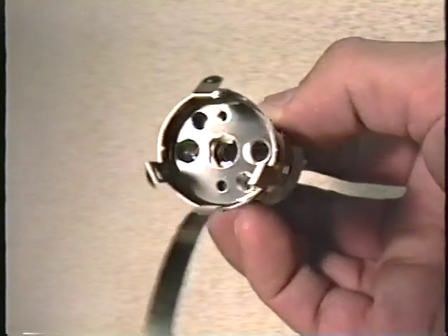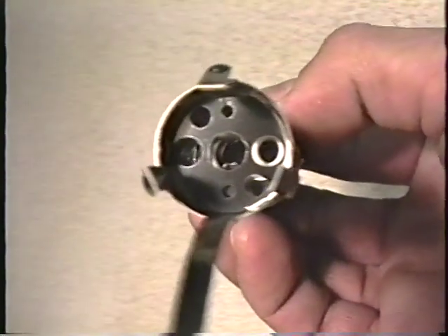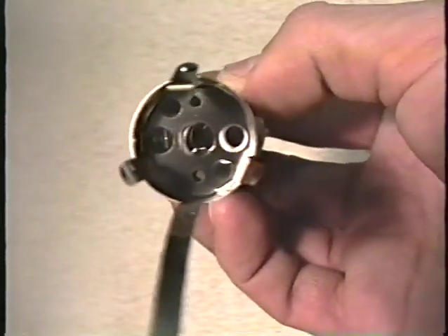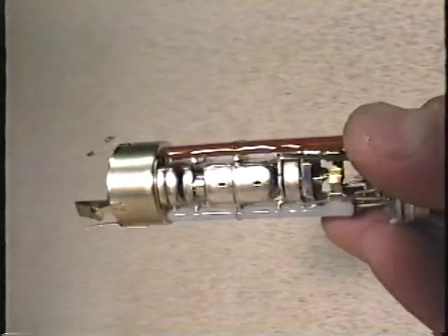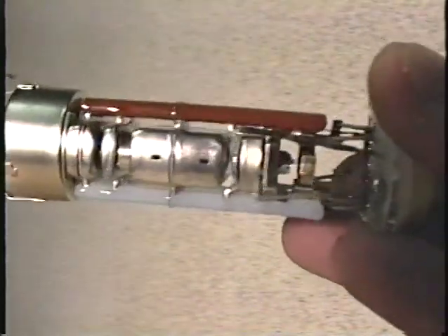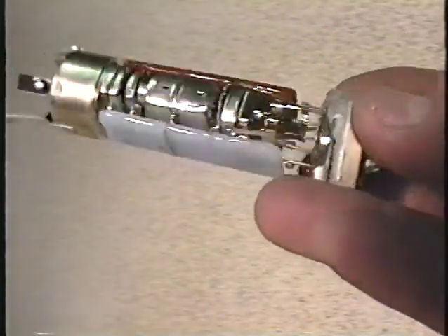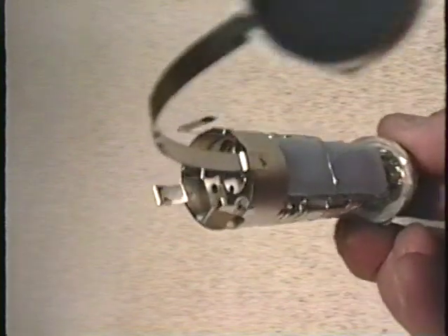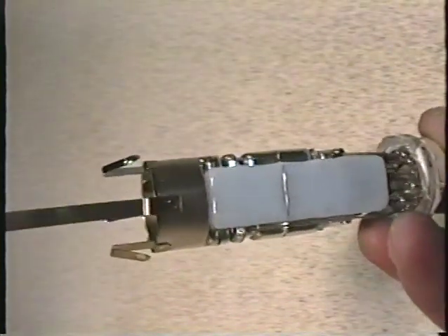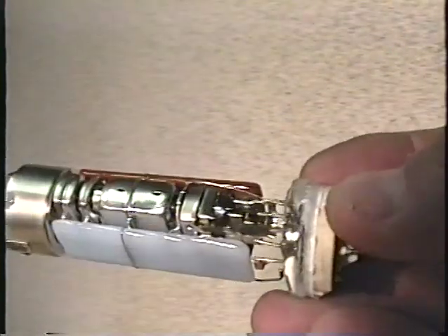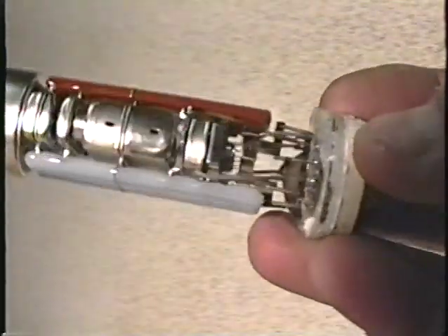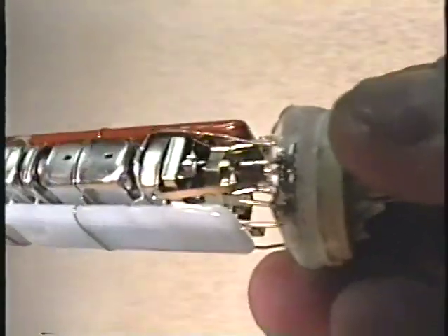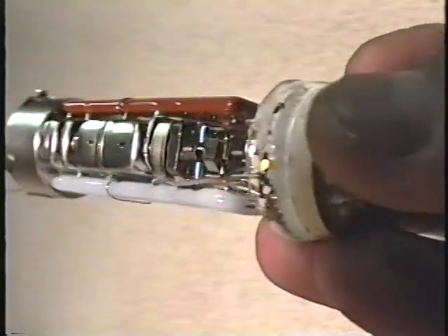See that? All right. Anyway, you can see the 3 holes where the electrons shoot out. Remember, the electrons are those little tiny negatively charged subatomic particles. Now, in order to get the electron gun to emit the electrons, it does have to be heated up. You know the orange glow that you see down here in the neck of the picture tube? That's what we call the CRT heaters. That's the CRT heaters doing their thing.